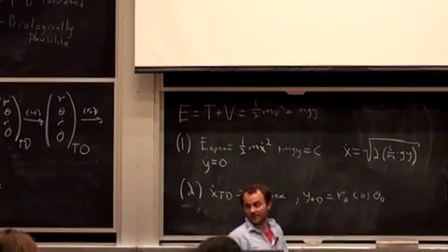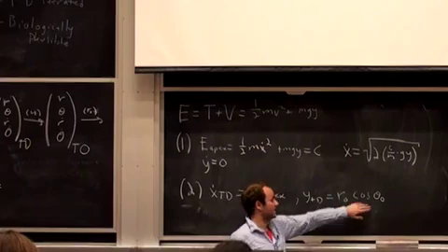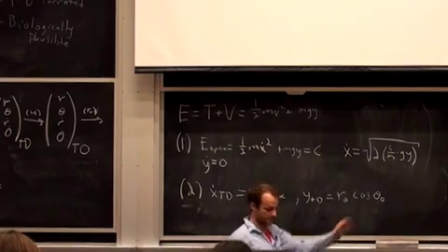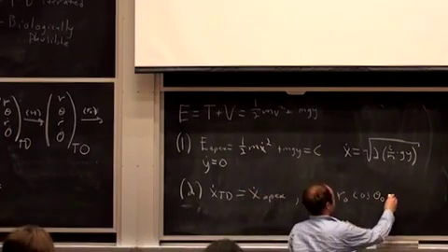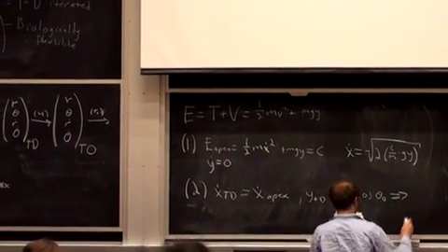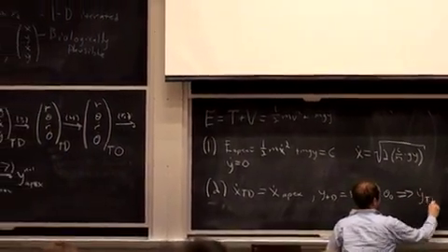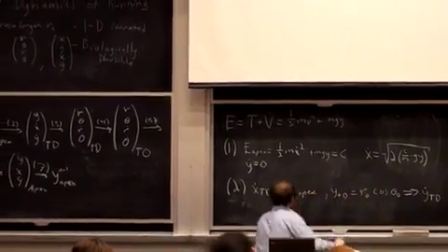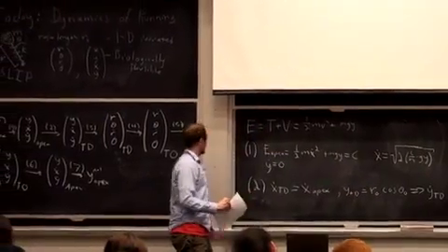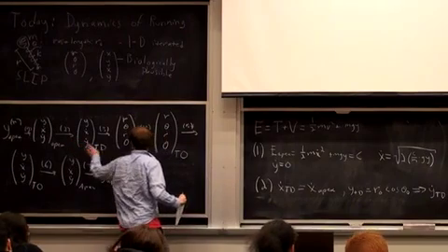This is what I was talking about with the desired theta: you know you're going to touch down at this desired theta. And since we know our energy, we can get y dot at touchdown. So that gets our transition from apex to touchdown.